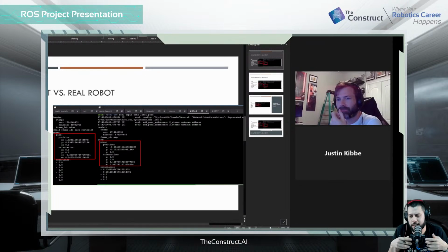You can adapt it later. You can go in the YAML file and change the origin and parameters of your file. But then that connection gets published, from map to odom, and then you can subscribe to the AMCL pose, because it's actually when you move it that it appears. So it's always with respect to that place where you started mapping.